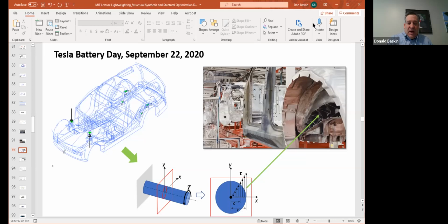And I think what Musk was saying is that it's probably so effective that now you don't have to have as much structure. You can bolt the rear cradle or suspension or rail structure, and the front rail structure and cradle, directly to the battery housing, and use that battery housing as the primary structure of the vehicle. Therefore you're getting two different functions out of that material, which means you're getting more loading per given weight. So that's what's so extraordinary about that idea.